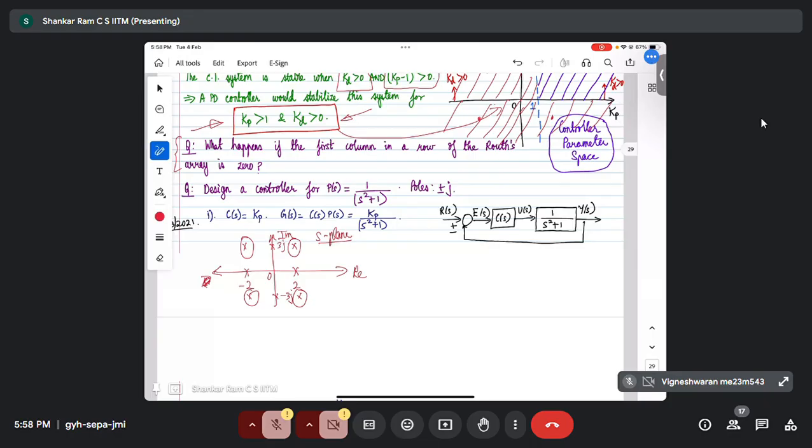So when the first term happens to be 0, you will have radially opposite roots. Whether you will have roots in the right half plane or not depends on whether there are other sign changes in the first column. But anyway, from a control design perspective, why did I not teach those subtle points in this course?